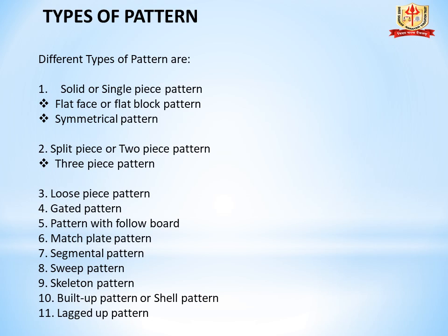Third is a loose piece pattern. Fourth is a gated pattern. Fifth is a pattern with follow board. Sixth is a match plate pattern. Seventh is a segmental pattern. Eighth is a sweep pattern. Ninth is a skeleton pattern. Tenth is a built up pattern or shell pattern. And eleventh is a lag up pattern. These are some types of pattern.